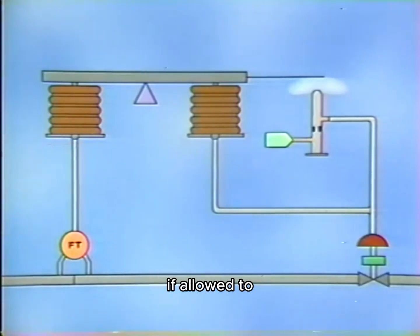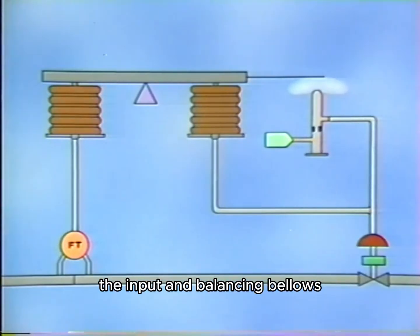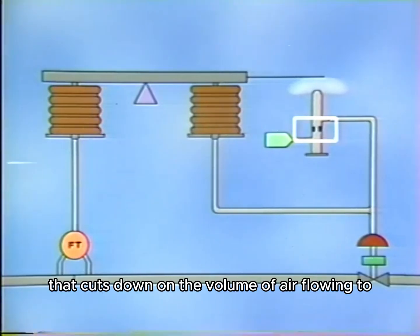If allowed to, the force of air flowing through the nozzle and against the flapper could throw off the balancing relationship between the input and balancing bellows. However, the forcing action against the flapper is reduced by using a restriction that cuts down on the volume of air flowing to and through the nozzle.